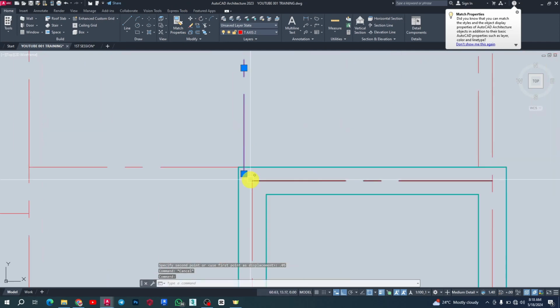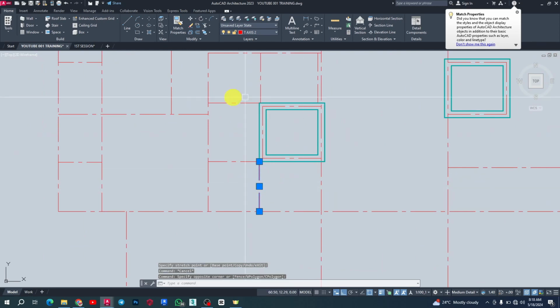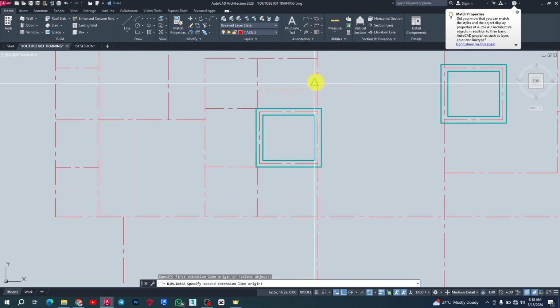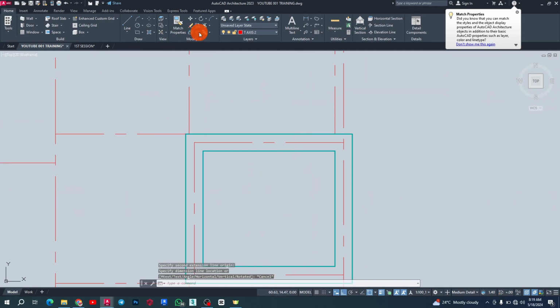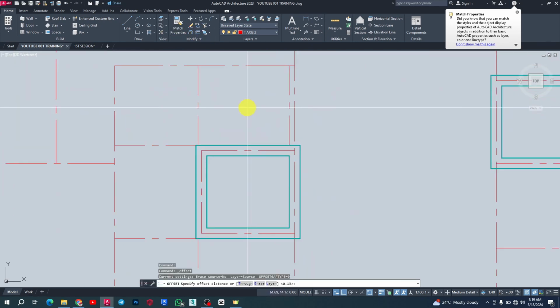So that I will have that space. Taking out 0.05 from this direction to 0.05, so that I have a section to host my formwork. So 2.1 divided by 0.3, since the width of my going is 0.3, that is 300 mm. So just offsetting this one.